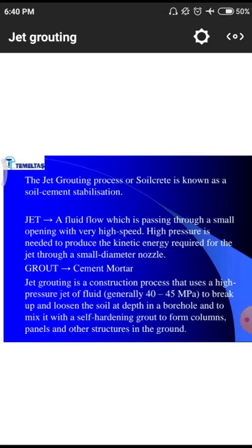For foundations with a larger depth, they use jet grouting with a force of 40 to 45 megapascals. The bonds between the soil particles are broken by the force exerted by the jet of fluid at a borehole, and the mix is self-hardening.